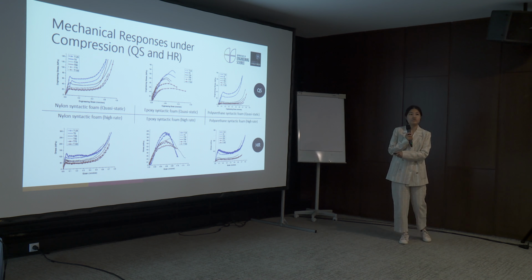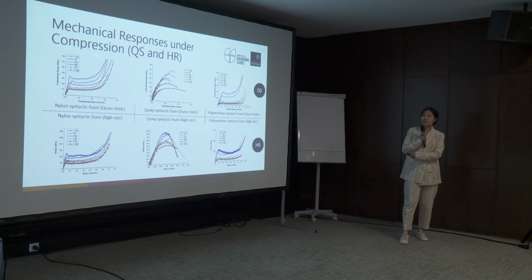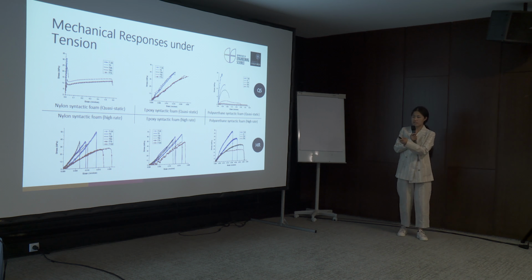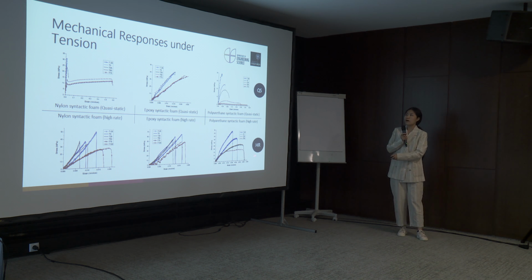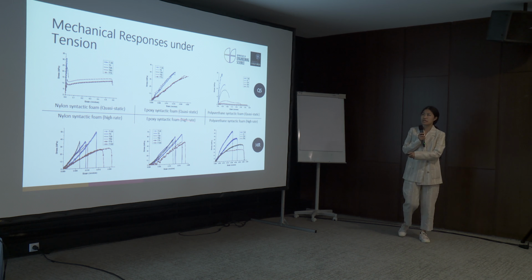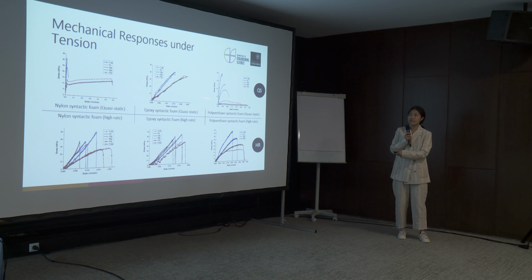and for all these three kinds of foams, it can be observed that these mechanical responses are all highly dependent on the temperature and the strain rate. These plots show mechanical responses of the polymeric syntactic foams under high rate and quasi-static tension at various temperatures.